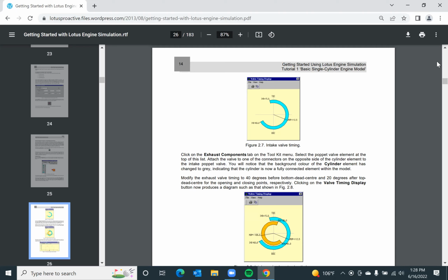But because of the finite inertia of the components, the exhaust valve should open before the exhaust stroke starts and should close after the exhaust stroke has finished. You agree with me? But that's again another problem. What is the problem? Then you have an overlap.